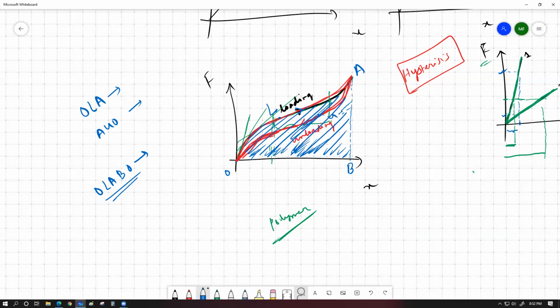Then this curve or unloading area, let's say this is the U over here. Let me just draw that U with the red maybe. This is the U, just a point to represent the different line. So the area under the unloading curve, which can be represented by A, U, O, B, A, represents the energy given up while unloading, which I can shade in red. This is the amount of energy that can be released from the specimen while unloading. So you can see while loading, it takes a bigger amount of energy compared to how much it gives out